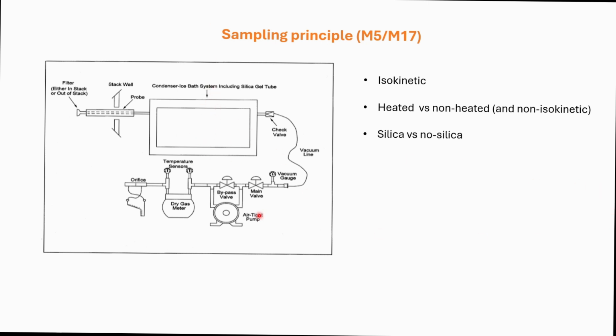And then just a note, typically inside this condenser you will have your impingers that you've put in water, and you force out condensation in those impingers, and then lastly you have a little silica gel trap. That silica gel trap will capture the last bit of moisture that you do not condense out.